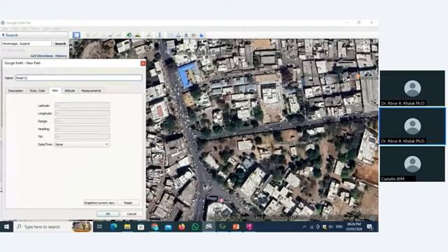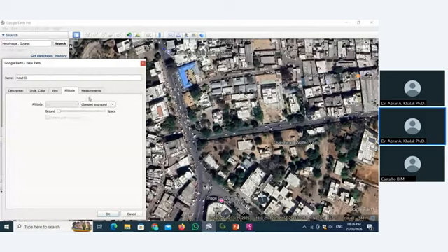You can view all the details. If I click here and take all the points, you can check all the heading range, and you can check the altitude and all the things. Whatever the road distance, you can decide here in kilometers. What is the real design industry workflow? If we take a unit in kilometers, and we decide that every 500 meters we are taking a center line point, then we have to take a point every 500 meters.